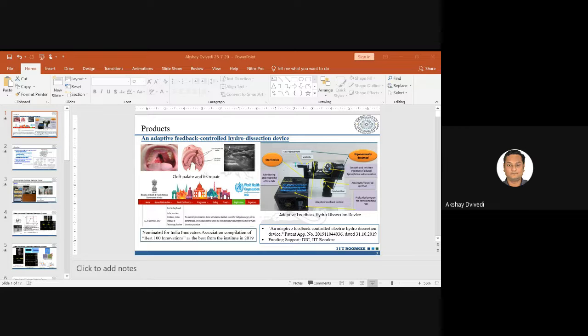The question that came up with respect to stakeholder requirement is, can you go much deeper? Can you go deeper than this 1350 micrometer? If you can do that, that is going to be quite good. Then you have a process which is economical, which is able to do multiple things, and that will fulfill all those customer requirements. So to do so, we identified that yes, the electrolyte needs to be replenished, and that replenishment has to be in line with the amount of electrolyte that gets evaporated.